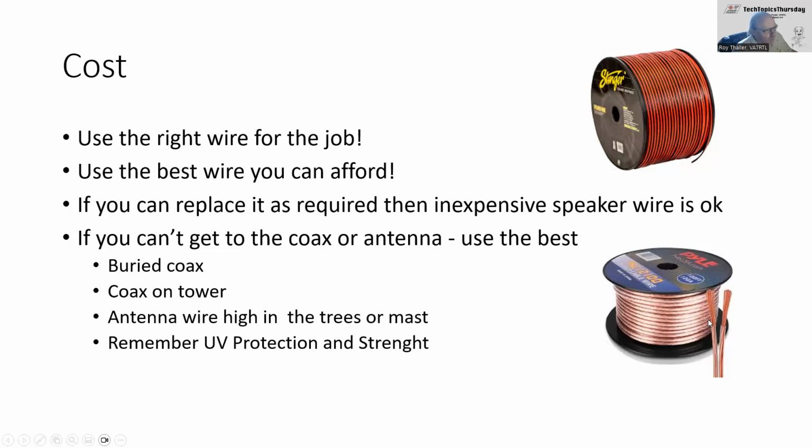So one of the things is that wire will stretch and eventually break through its own weight. The other thing you have to remember also is that a lot of insulation is not UV resistant. So if you're outside, you should have insulation that provides some sort of UV protection. If the insulation breaks off and gets damaged, then water can get inside, and then water causes corrosion, and then creates also a stress point.